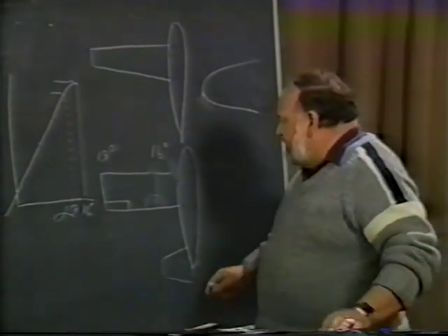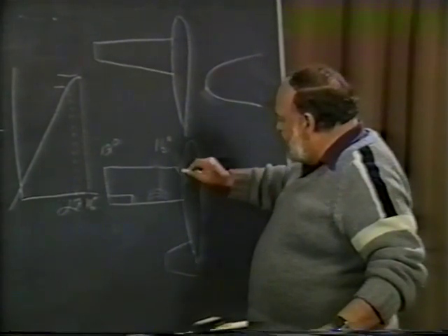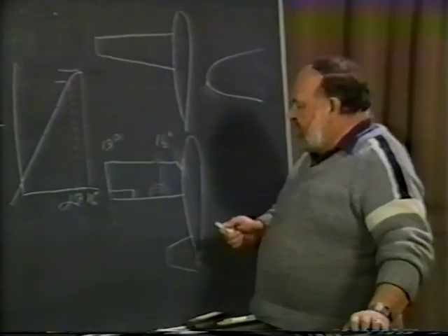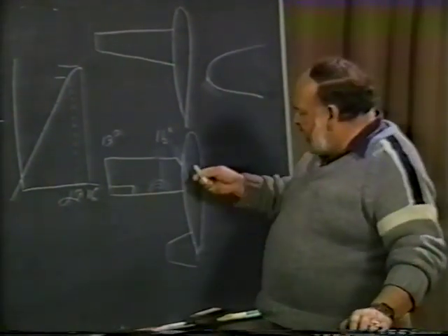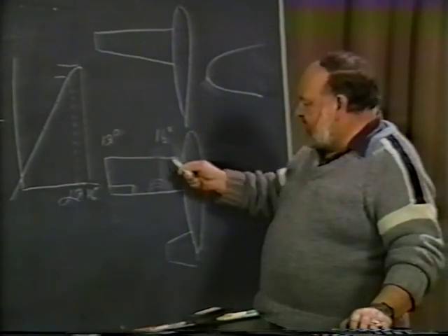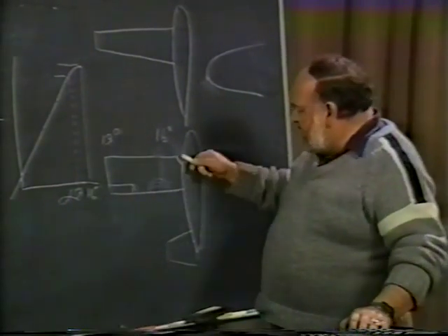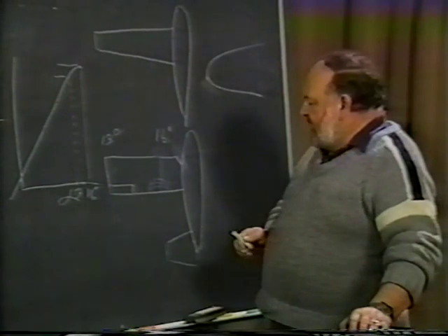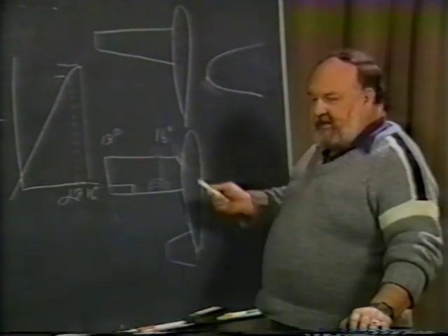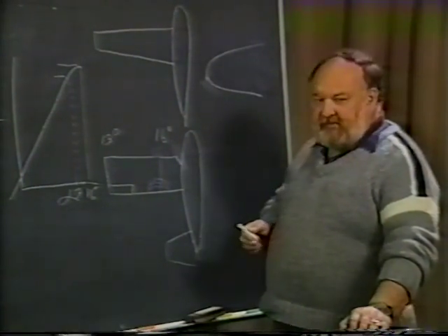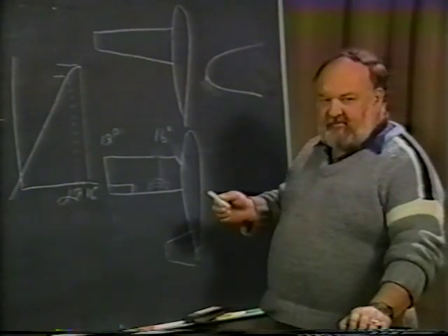one thing can be done, and this is where Steve Wittman was very brilliant on his design of his Tailwind. Take a look at a Tailwind and look at the planform. What do you see? You see a little notch here in the wing. You have the straight leading edge, and then you see a sweep back of the leading edge right as it meets the fuselage. Well, he's done it for several reasons, very cleverly.